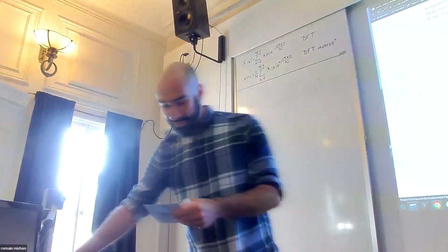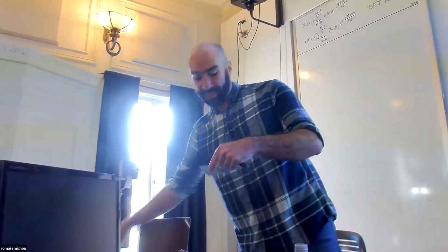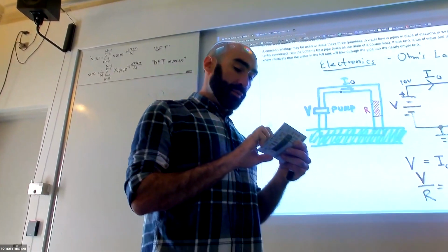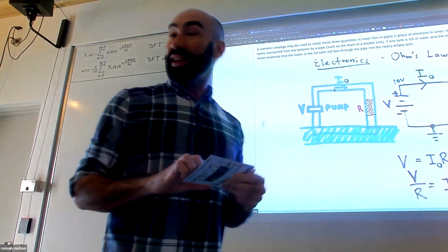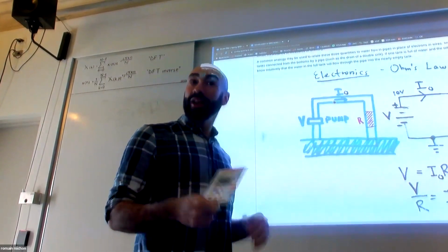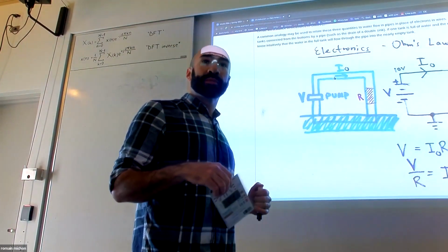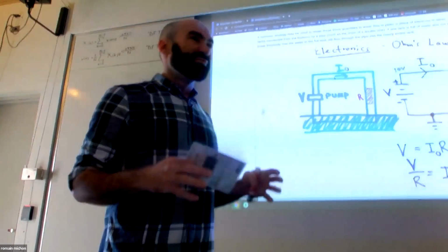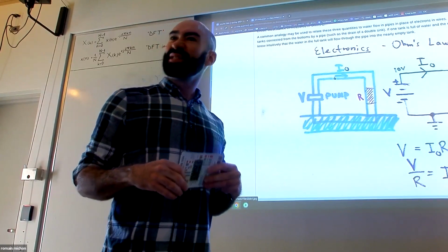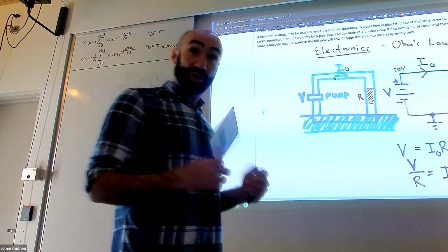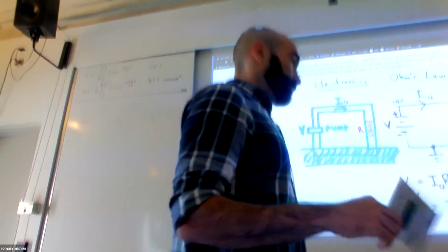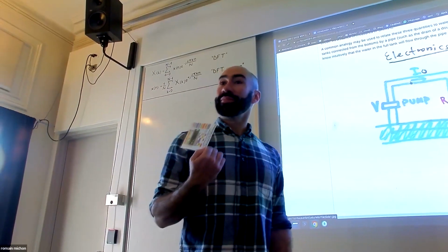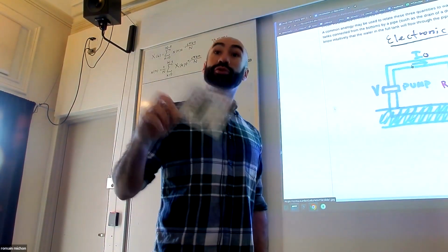pinout card, it actually says that the 3.3 volt pin can only give you up to 250 milliamps, which is very, very, very low. Okay, 250 milliamps, you can basically probably power, I don't know, like 8 LEDs, 10 LEDs, or something like this, which is not a lot. So it means that with the Teensy, you're never going to be able to power something big. That's something you should keep in mind.